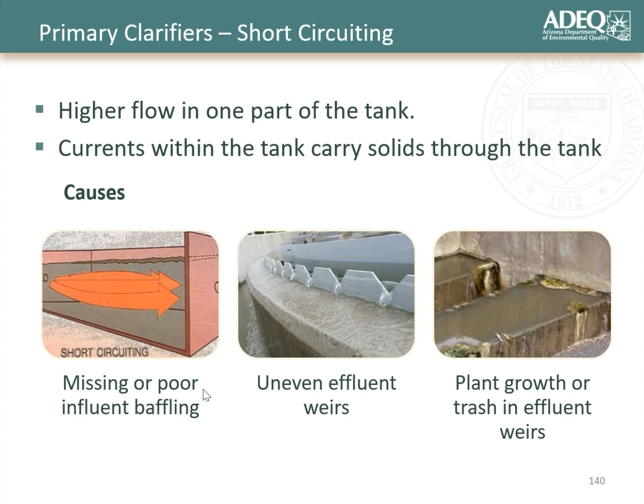One thing I've seen frequently is uneven effluent weirs, in which a weir on one side is lower than the other. So then the water wants to go to that lower side, and the other side is less loaded. And so then you get much more hydraulic loading over one spot and causes a flush out that could happen there at that particular low spot in the weir.